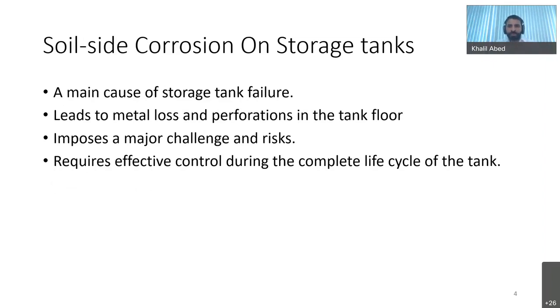It's important, as a start, to remind ourselves of the significance of the soil side corrosion problem for aboveground storage tanks. We all know it's a principal cause of storage tank failure, as it leads to plate thickness loss, holes in the tank floor, and eventually leaks, which impose major environmental risks and operational challenges to tank owners and operators, who always aim to find an effective control method for this type of corrosion during the complete life cycle of the tank.